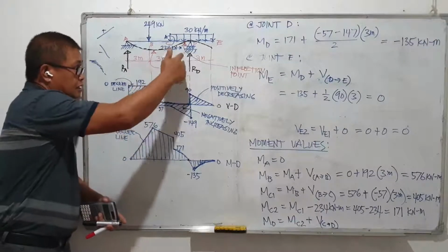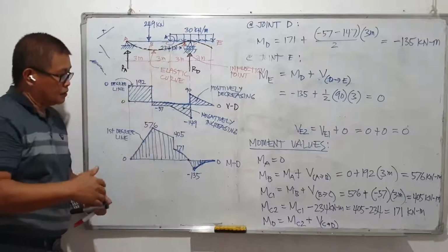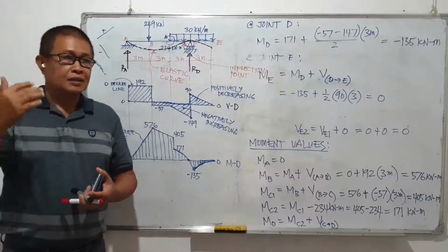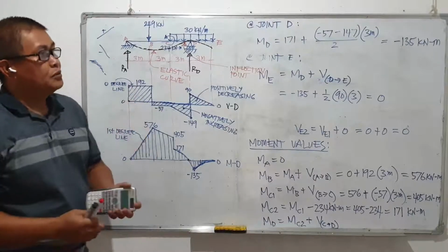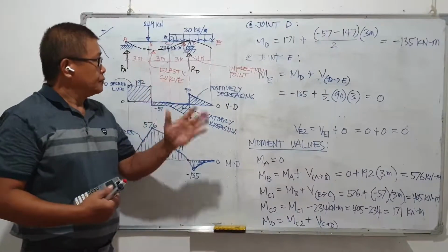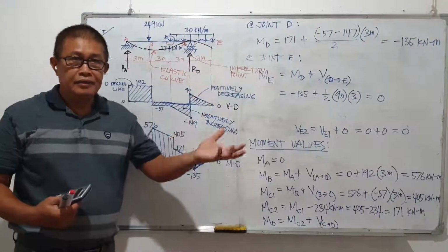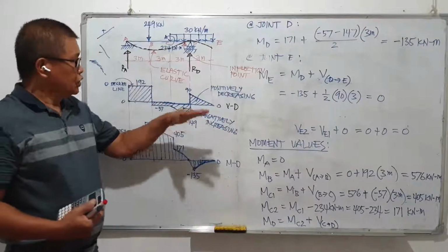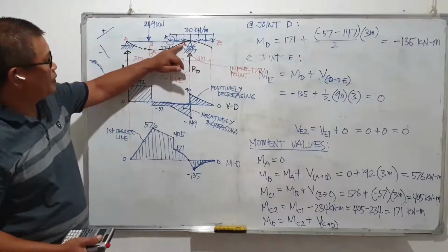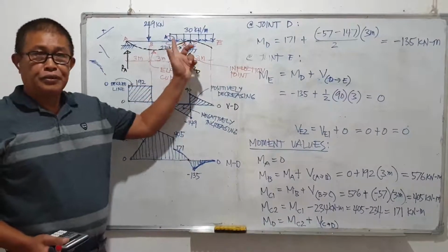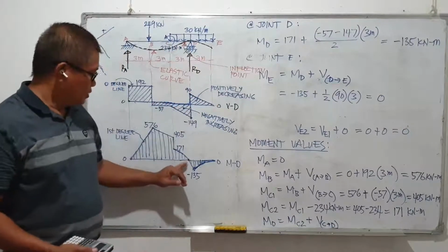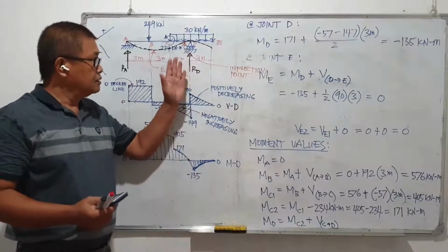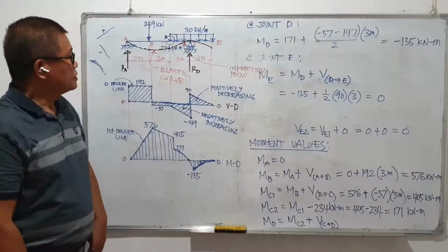And this inflection point again is also where we can stop the pouring of concrete beams. Sometimes we may be stopped by heavy rains, or some phenomenon that the pouring may not be continued. So as much as possible, we have to stop the pouring at the location of the inflection point. Because again, there is no stress, the fact that there is no moment. It is dangerous to stop or to have the joint in our reinforcements elsewhere.